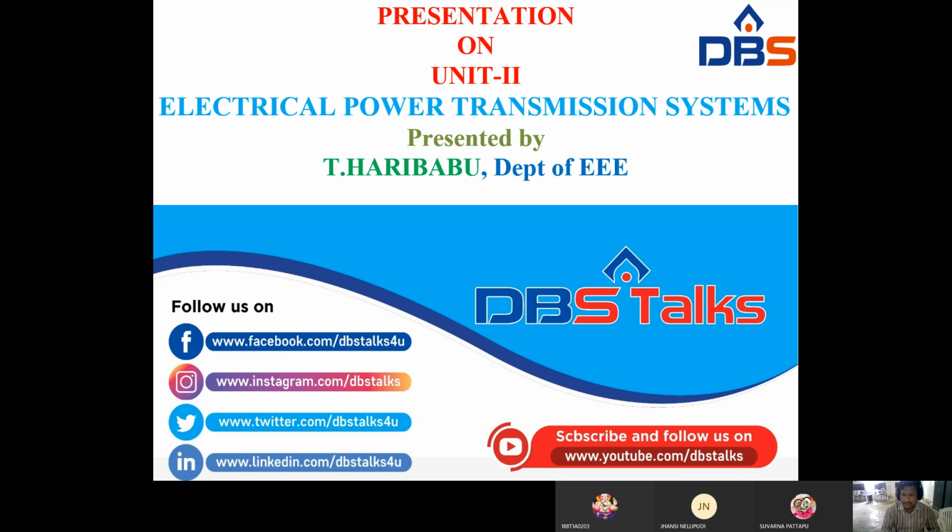Generally, two-port networks are classified as Z parameters, Y parameters, ABCD parameters, H parameters, right? Coming to the Z parameters, the input voltage and output voltage V1, V2 must be expressed in terms of input current and output current I1, I2. V1 is equal to Z11 I1 plus Z12 I2.